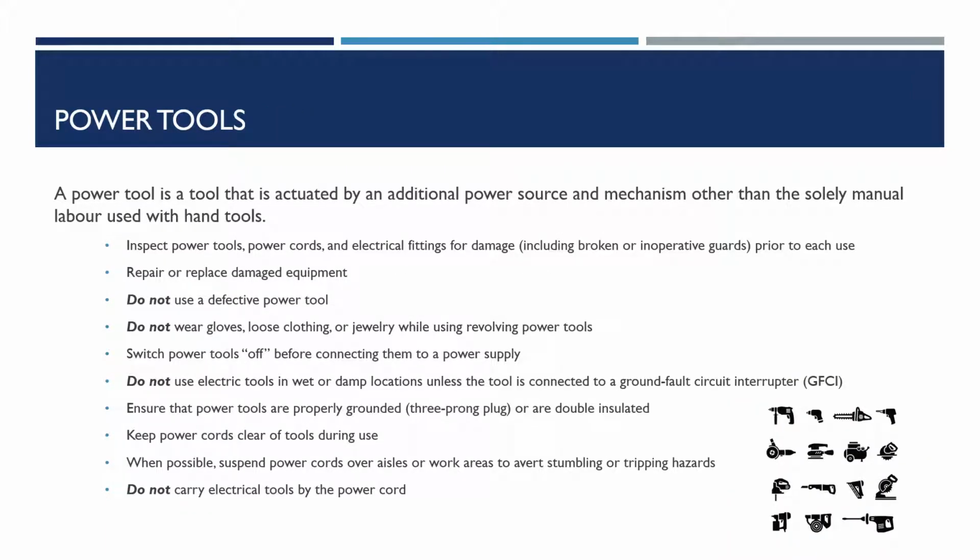Power tools. A power tool is a tool that is actuated by an additional power source and mechanism, other than the solely manual labor used with hand tools. Inspect power tools, power cords, and electrical fittings for damage prior to each use. Repair or replace damaged equipment. Do not use a defective power tool. Do not wear gloves, loose clothing, or jewelry while using revolving power tools.